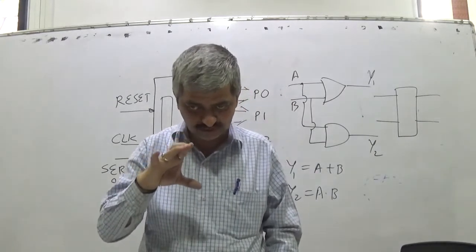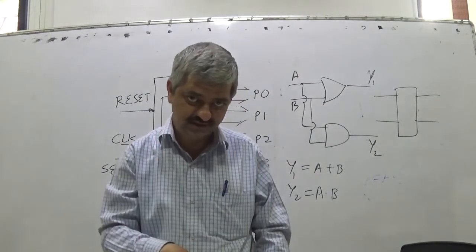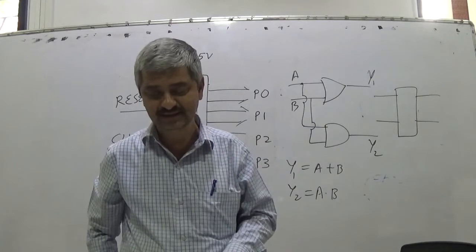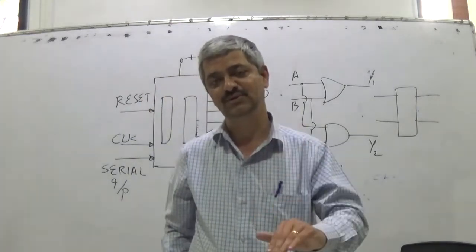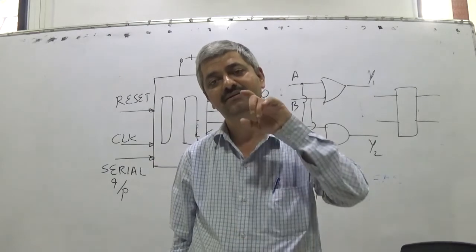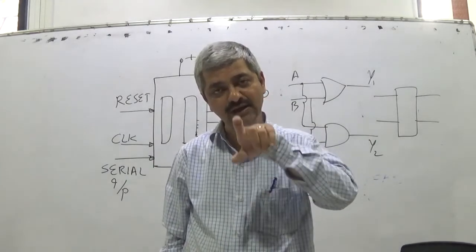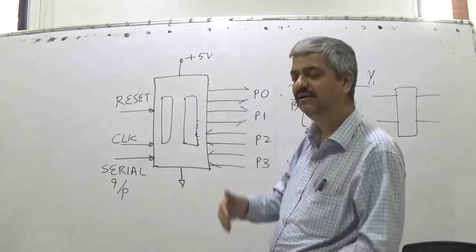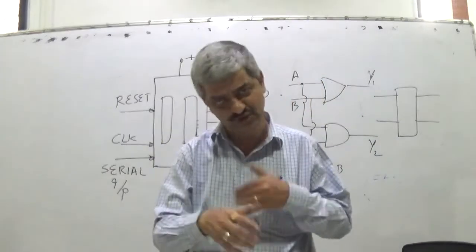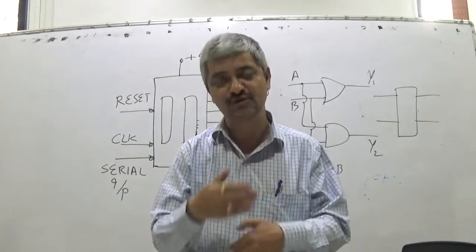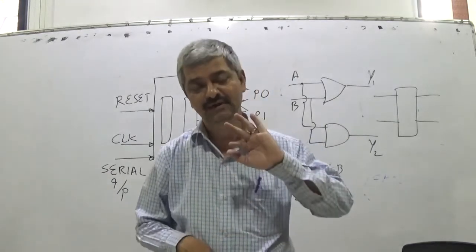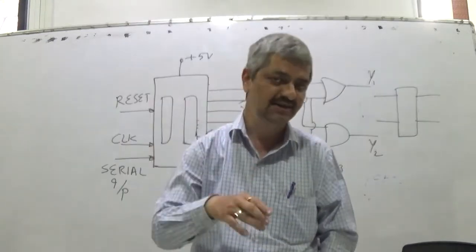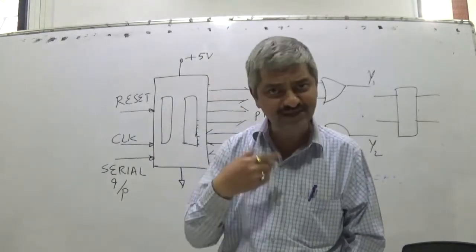A microcontroller chip comes with, just as an example, 32 port lines accessible to the user, and the program refers to these pins and does something based on the status of the different input pins, and activates different output pins in a structured manner. That program resides there, and you can change it the way you like.